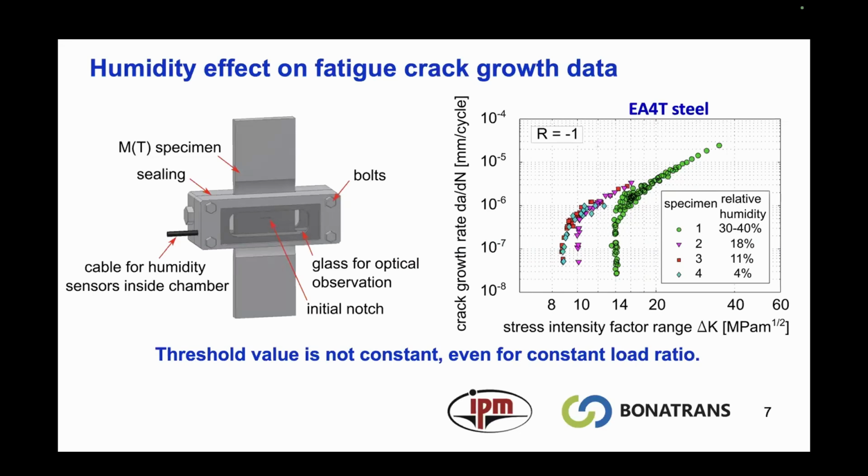Here you can see important results from this part of research. It is the change of threshold values of the stress intensity factor for normal laboratory air and for dry air. This decrease of threshold is very important and can influence the result of your lifetime estimation.